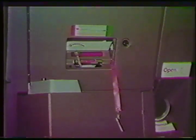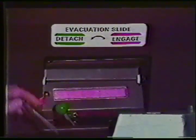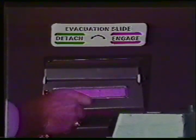When the slide is engaged, the door is air assisted. It therefore must be released quickly after pulling up the operating handle. The prescribed method is to pull up and immediately open the palm and push away. To engage the door before takeoff and landing, the pin must first be removed and then move the lever to the engaged position. In the event of an actual emergency, ensure the door is engaged and then open it. Pull up, open palm, and push out.